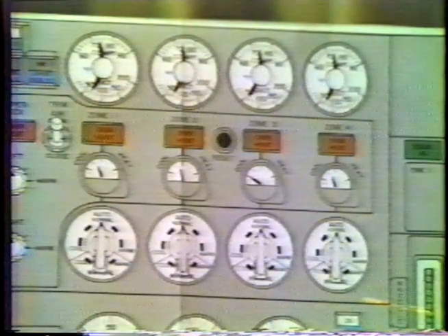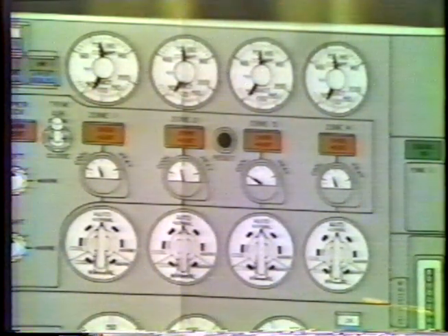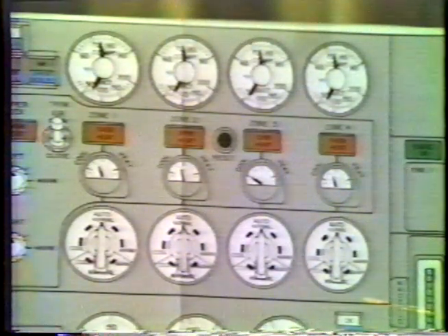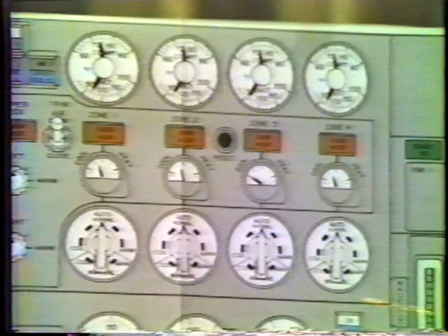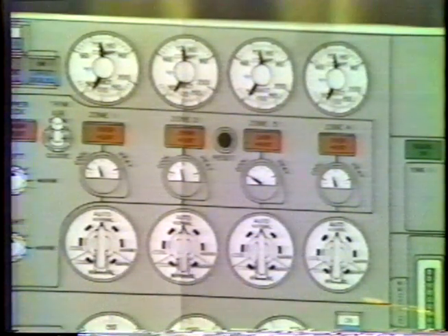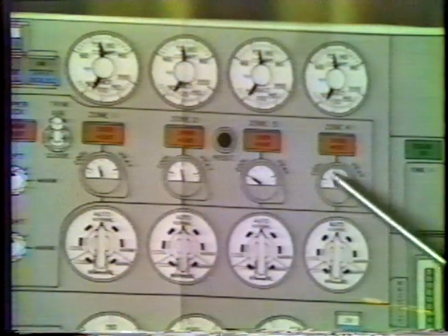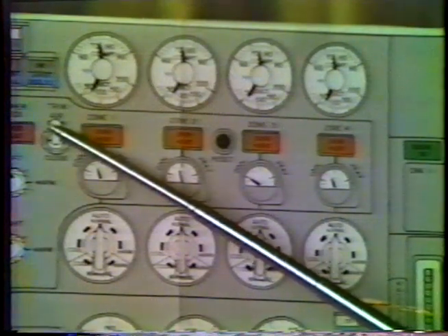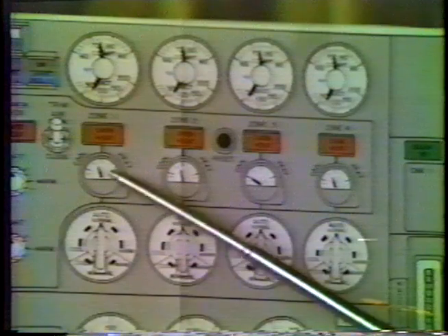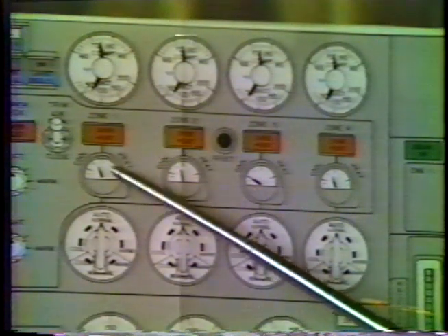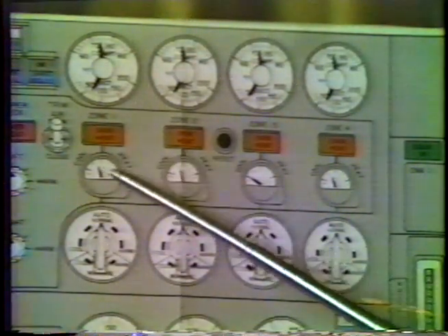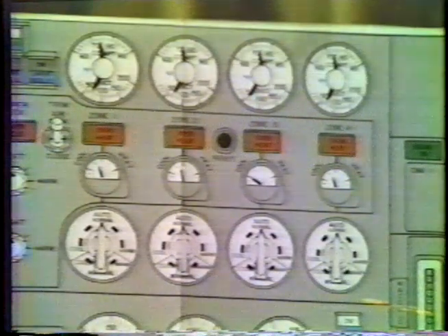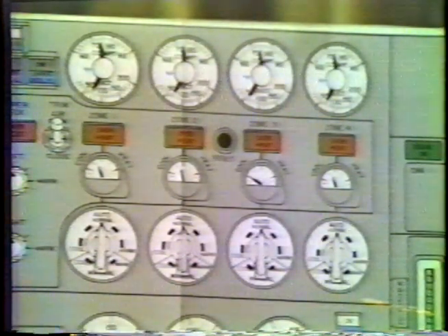The amount of conditioned air going to each area is tempered by a small amount of hot air, which is controlled by a trim air valve. The trim air master switch controls all trim air, and at each area there is a small control valve which adds air to the conditioned air to bring it up to the temperature required for that area.